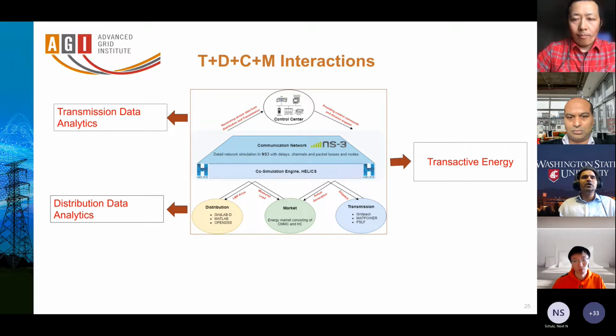There are very few business models in North America as well as in Europe, but research is still going on around the peer-to-peer market. The advantage of the peer-to-peer market is that it reduces network congestion, because you are utilizing resources locally, within the community where the prosumers or distributed energy generators are, and selling their generation to the neighborhoods or nearby communities. So you're not dispatching the power to the central operator, reducing the overall burden on the distribution system or the operator side.